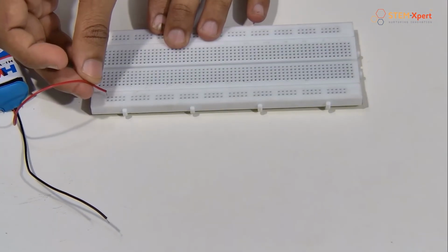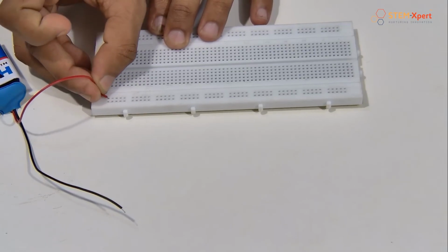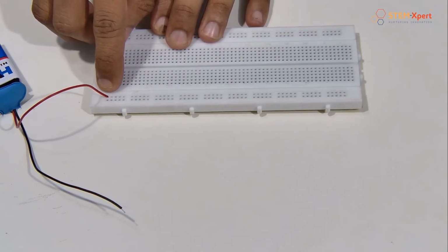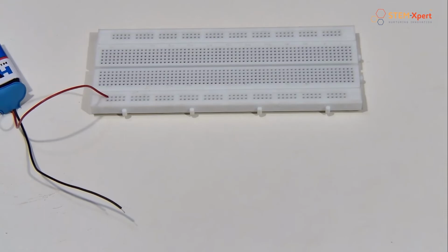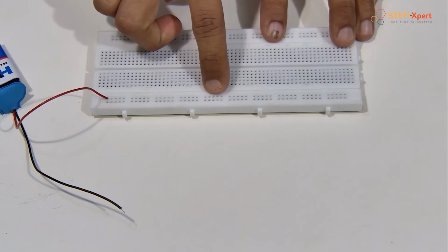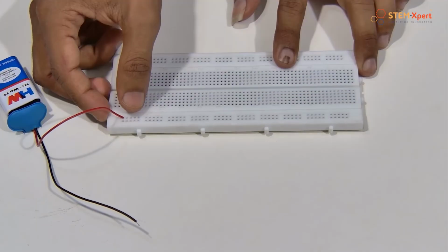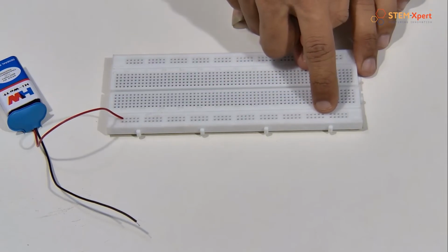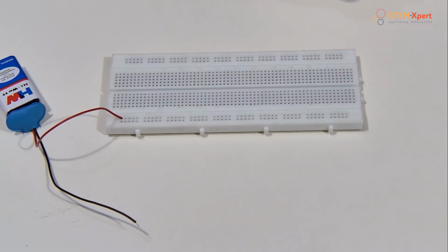So what about this one? Yes, if we apply a positive voltage here, then what happens? It will act horizontally, right? Yes, that means if I apply positive voltage here, then I can get the positive from these entire points up to 5 sections. I have already mentioned, 1, 2, 3, 4, 5. These 5 sections are mutually interconnected. After this 5th section, there is no interconnection. You can get the positive from only these 5 points. If you want a positive from the other points after the 5th section, then you can use jumper cables or wires. I hope you have understood.